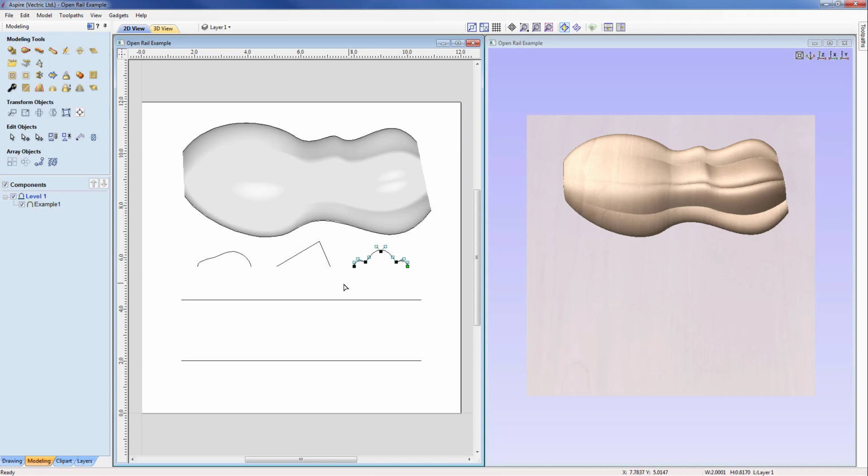Okay, and these will have a direct effect on whether we can use that command, sweep between spans. So with this, I want to gain a bit more control. Ideally I want, for instance, the top node, the middle node, to be transitioning into this node on the rounded shape. Now if we look at it normally from a typical 3D view, it will be doing this by a planar transition, so it will not be blending from node to node. But because we have the same number of nodes and the same number of spans, we can switch that on and gain greater control if I wanted to transition node to node.